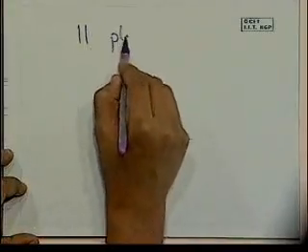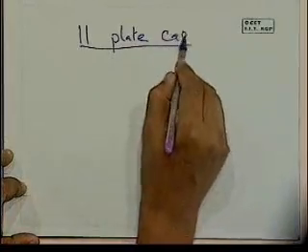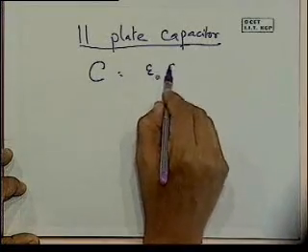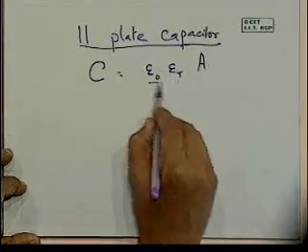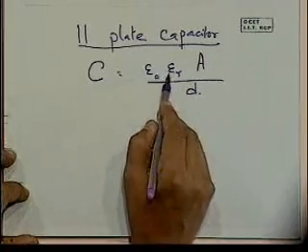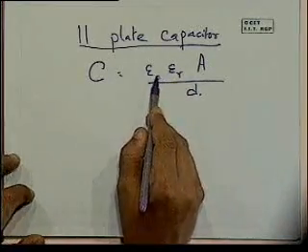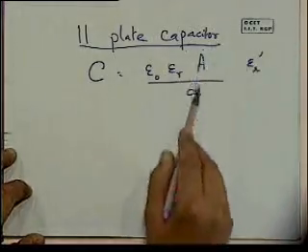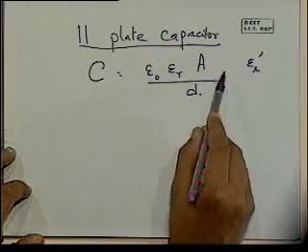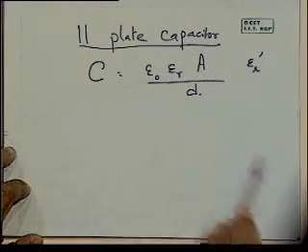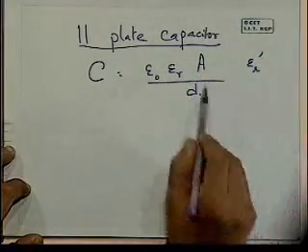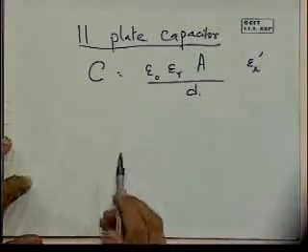Okay, let's look at the parallel plate capacitor equation, which we have seen earlier, and we come back time and time again. Simply that C is equal to epsilon naught epsilon R A by D. Now this epsilon R that we're talking about in this original equation that we've been using for a while, it's basically the value of epsilon R dash, what we had in the complex permittivity. The real part of it is what we're going to use in a calculation like this. If you remember, the double prime one in the complex was related to loss. So this is the one that is related to the actual values that we're going to use.